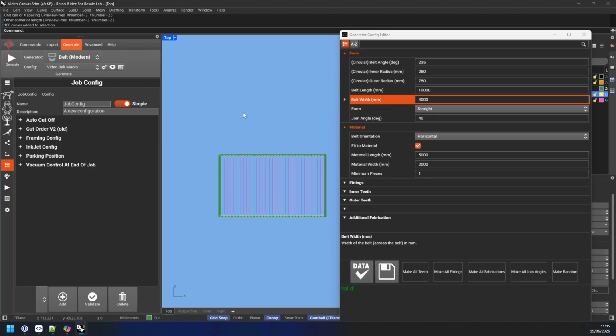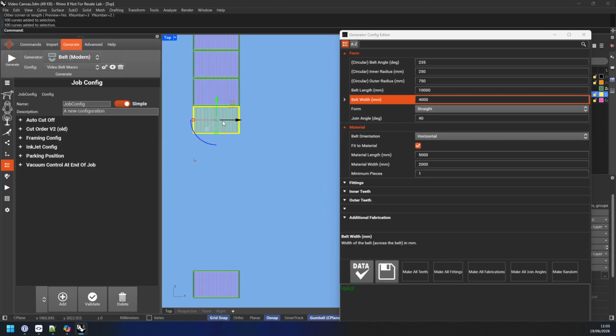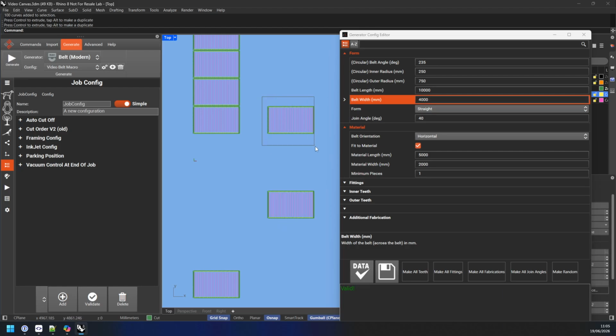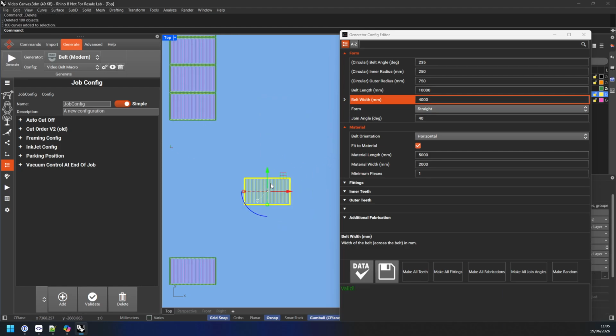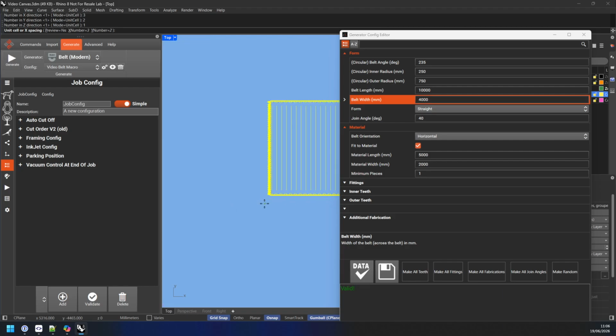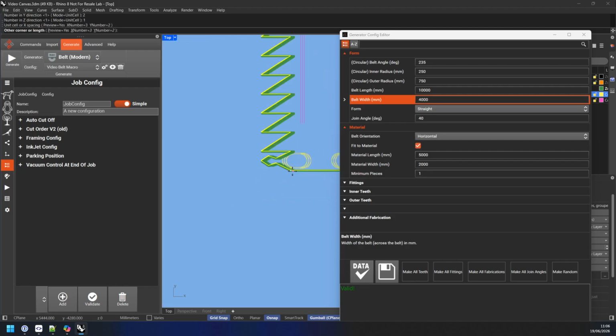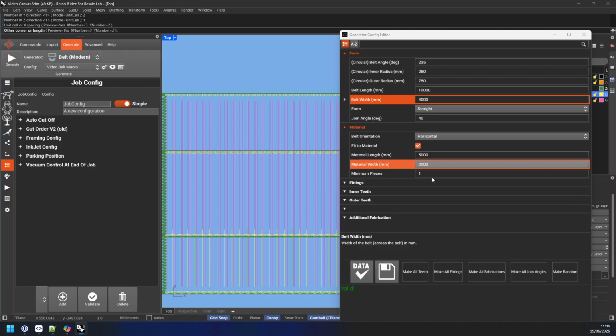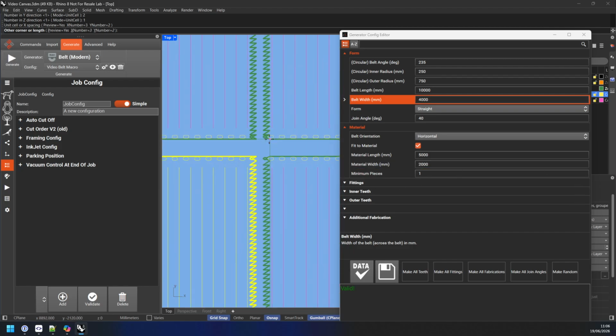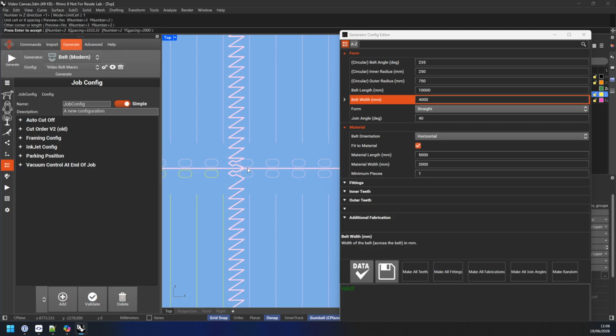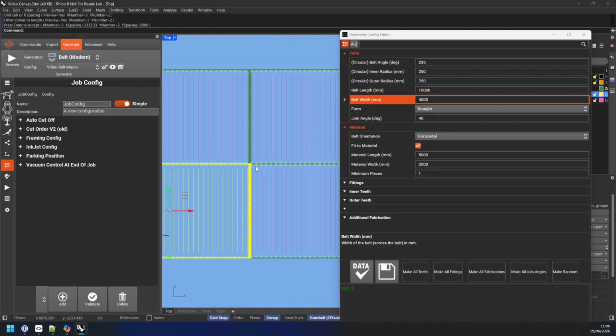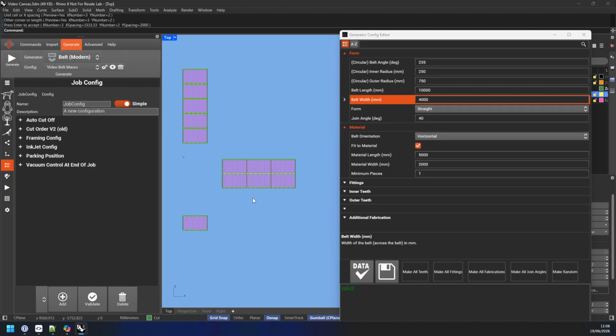That was my fault. I've done that wrong. I should have selected to the opposite corner. Let me do that again. So if you hold down Alt and then use these arrows, you can create copies. So if I do that again, we're just going to array 3 in the x direction, 2 in the y direction, 1 in the z direction, and the spacing is from this shoulder all the way to this point here. You'll see that then generates our belt.